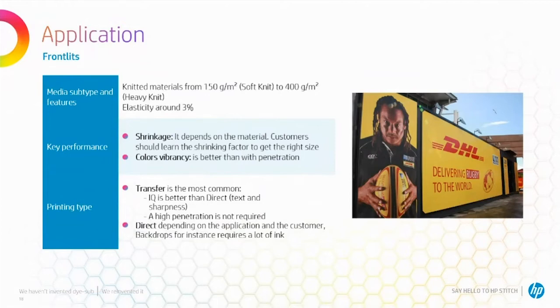Fabric, once it's heated up in your heat press, is going to shrink. The mills or the fabric manufacturers heat set their materials at about 390. So if you run 390 in your dye sublimation calender process, then you're going to see very little shrink. If you run 400, even if you go up to 410, you're going to see more shrink because it's more heat. And if you have to run longer, more time in the higher heat, if it doesn't scorch the fabric, then it's definitely going to shrink up a lot more.